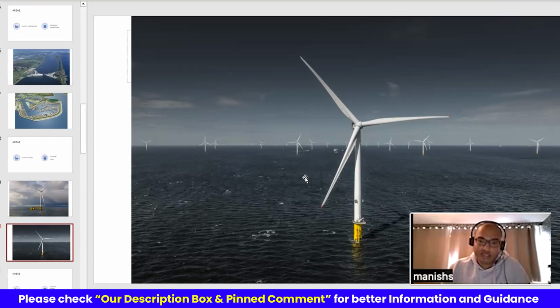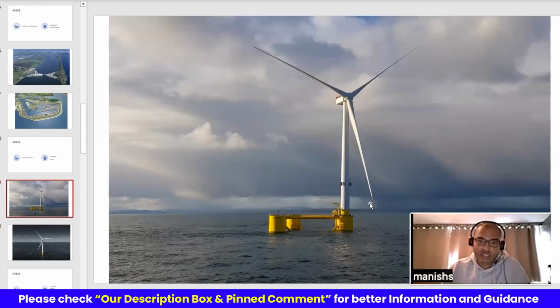In this slide you see a fixed wind turbine, and in this slide you see a floating wind turbine. So you have a huge floating structure. The length of this triangle may be something like 100 meters, and you have catenary chains connecting these huge floaters, which are 70% inside the sea, so you cannot see them. And you have huge mooring lines connecting them to the seabed, and these are going to stay in the field for 20, 30 years.